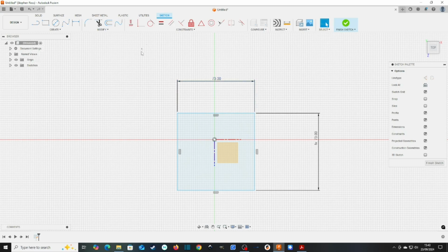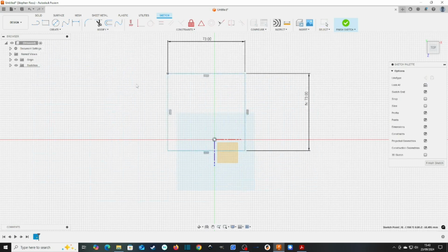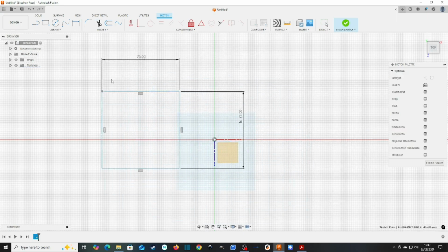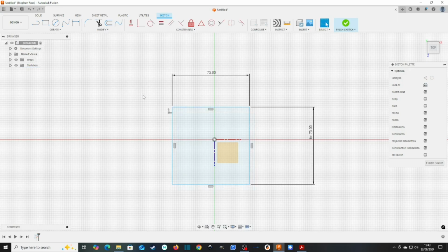Anyway, the next thing I need to do with this constraint is, whilst the physical geometry is fully constrained, where it is in 3D space is not constrained. So the easiest way I've found to do what I want to do here is to draw a line. So just up in the create tool and look for this little triangle here. So if you highlight over a bit of geometry, it will snap to it.